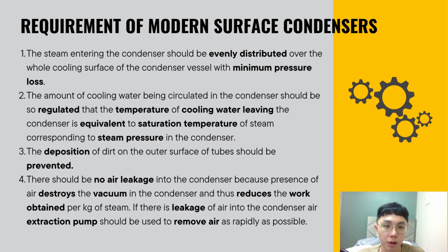Next, these are the requirements of the modern surface condenser. The first requirement is that the steam entering the condenser should be evenly distributed over the whole cooling surface of the condenser vessel with minimum pressure loss.